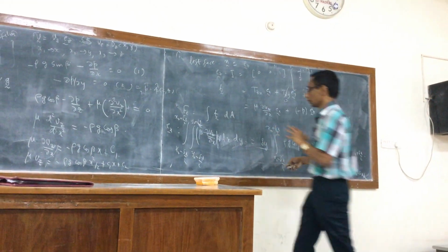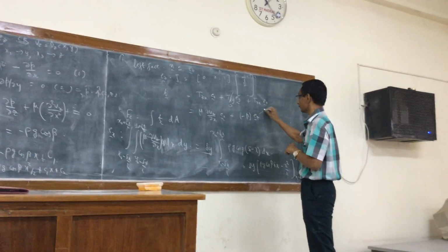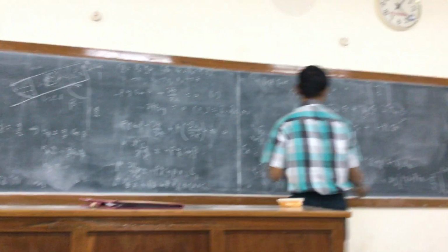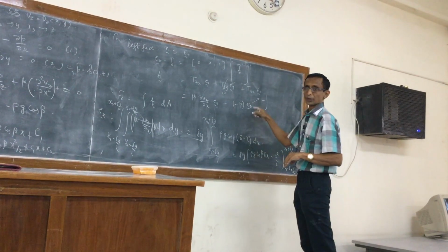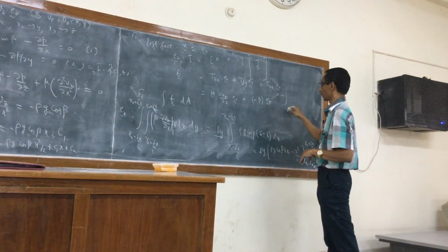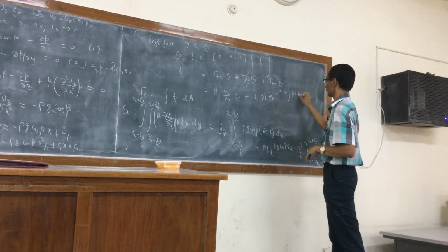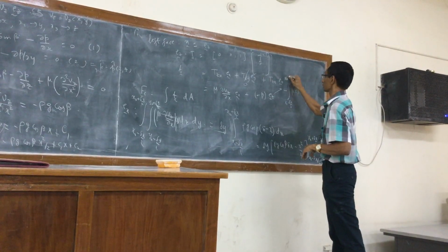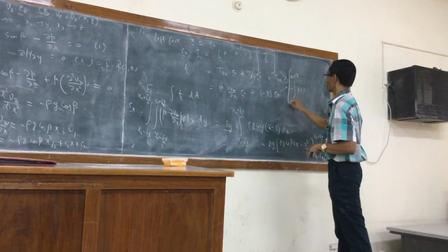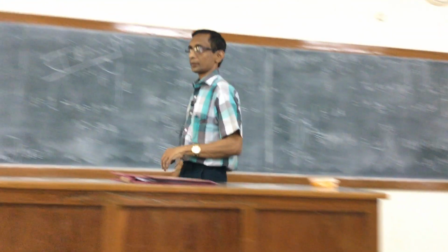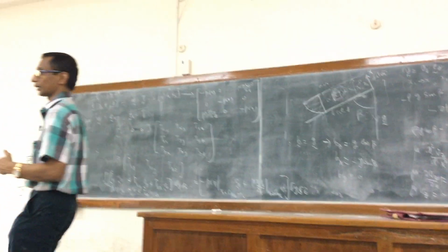So for p, the procedure would be the same. The z component would involve minus p, for which we have the expression. So minus the z component of the contact force would be minus the integral of p of x, again from x0 minus delta x by 2 to x0 plus delta x by 2. The whole thing multiplied by delta y, because there is no variation of the integrand with respect to y.